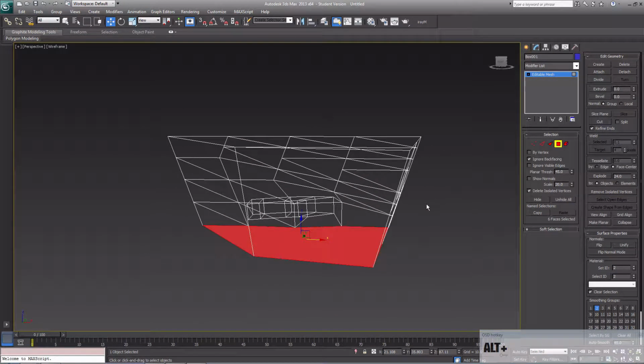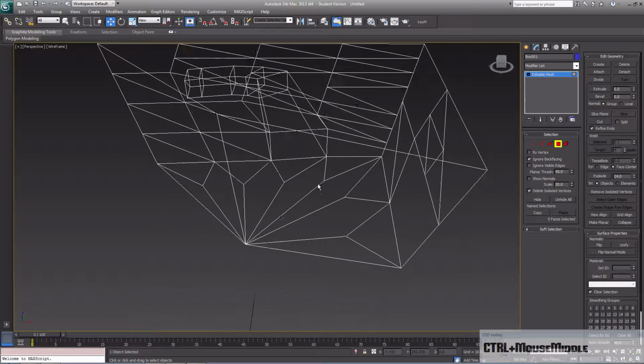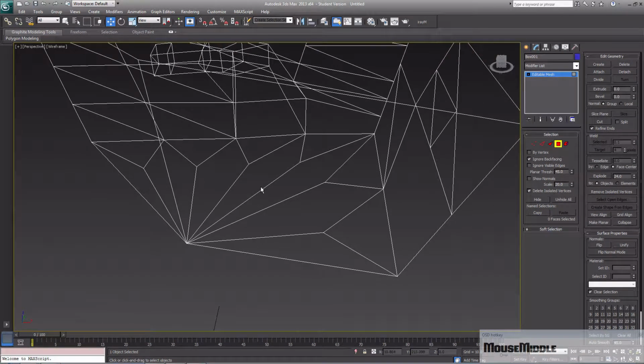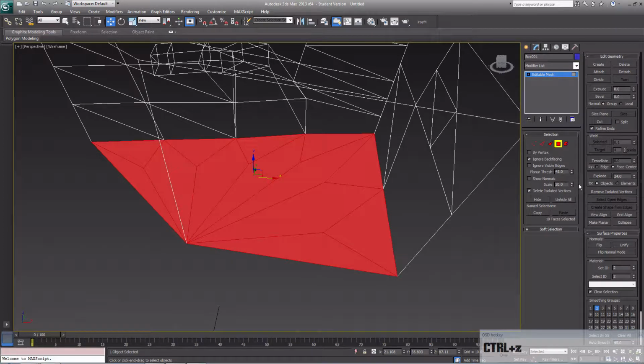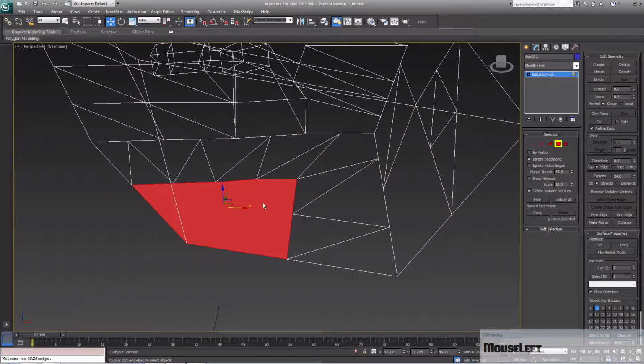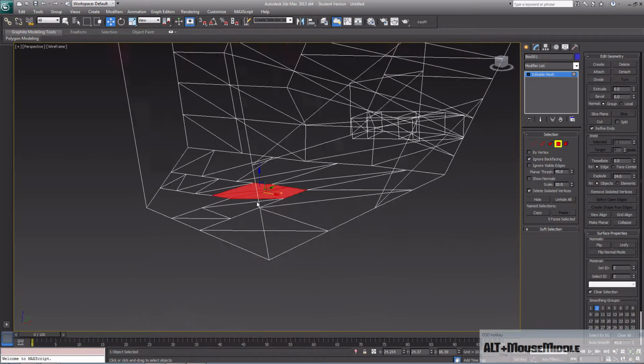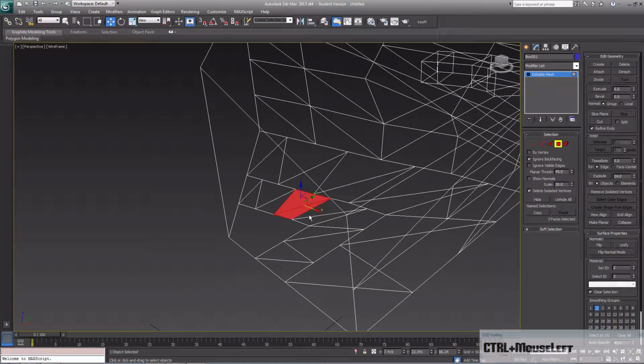I used edge because it gives you the squares, which I wanted for a square tunnel. Let's try face center now. And you'll see it gives you this weird, more flower or star-like pattern. That's not exactly what I want for a base either. I do want the squares. So I'm going to go back to edge, tessellate it by edge, and just keep doing that until I get a nice square area. I think this is about as close as I can get. Right about here.